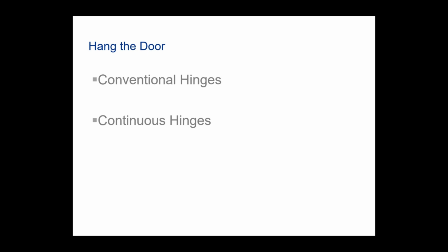When you're using conventional hinges, the load of the hinge is primarily at the very top of the door, and what that does is it creates a lot of wear and tear, not only at the door and whatever's connecting that door, whether it be hollow metal, aluminum, or wood, but it also puts a lot of load at the hollow metal frame or the wood frame, and that reinforcement that holds that together.